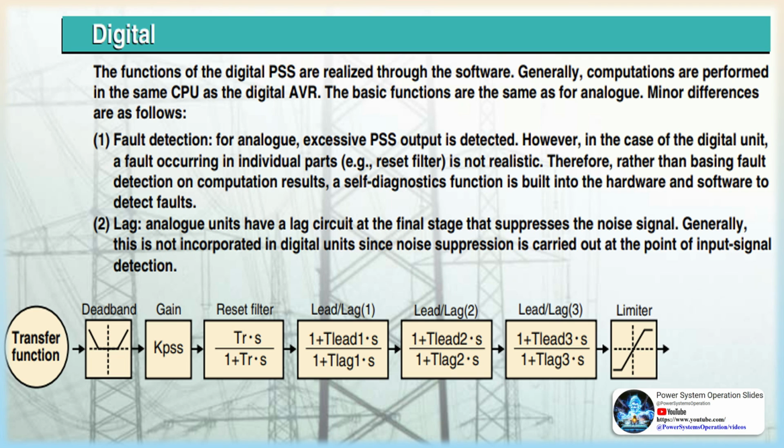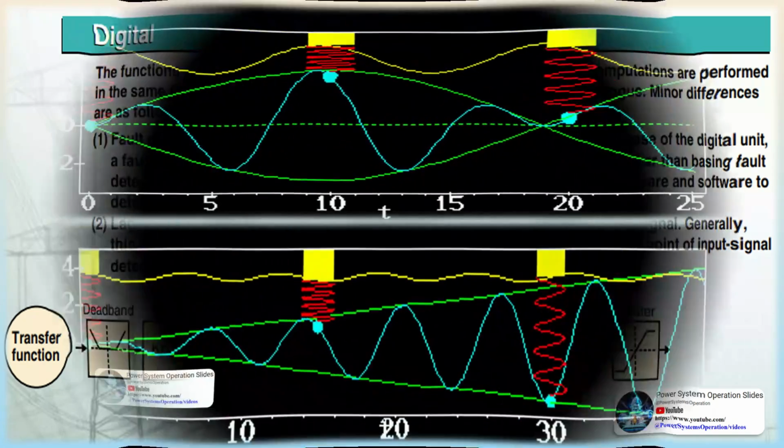Rapid small positive and negative changes in frequency in the range of 0.2 to 3 Hz, called frequency oscillations, occur in bulk electric systems due to small variations in load. These oscillations must be damped (reduced) to avoid the potential for growing oscillations that could ultimately push frequencies outside of system tolerances. If this happens, the system will begin shutting down to protect equipment, thus resulting in wide-scale outages.